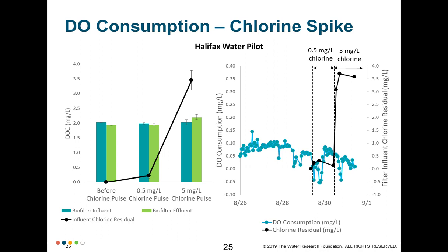However, the DO concentrations were quite low to start. I mentioned earlier the Halifax Water pilot, which had relatively low bioactivity. So it's not a perfect data set, but we did see a decrease in the DO consumption when we added the chlorine spike.